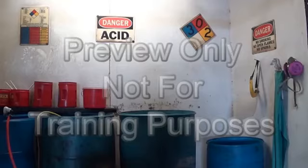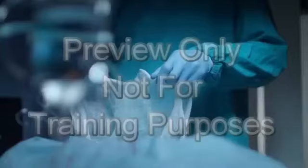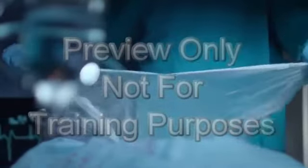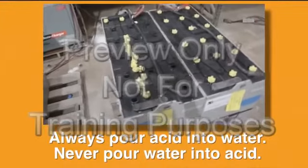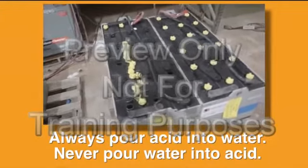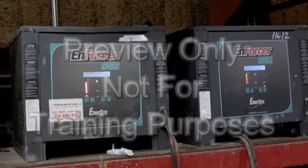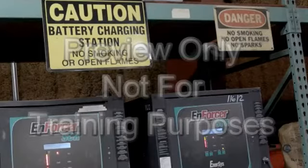Battery acid, a strong form of sulfuric acid, is corrosive and can cause severe burns. Remember, when charging, pour acid into water. Never pour water into acid. Flammable hydrogen gas is always present when charging batteries. It is potentially explosive and should not be allowed to accumulate in the charging area.